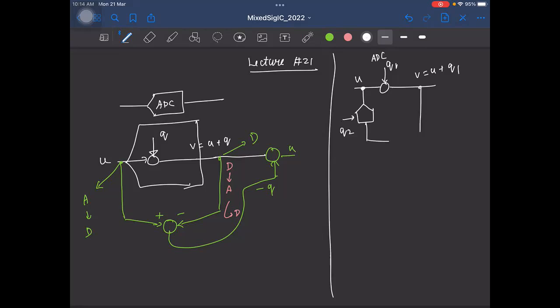Okay. So you understand till this point, right? We are doing the basic to improve the performance of the ADC. Basically, what we are saying is that some signal U, to which we are adding this analog quantization noise. So how are we going to improve the performance? The point is, if you don't have Q at all, you get an infinite resolution ADC, right?